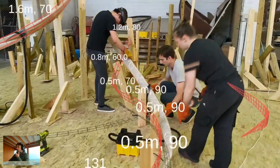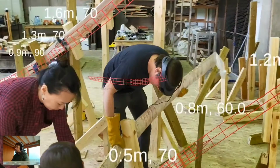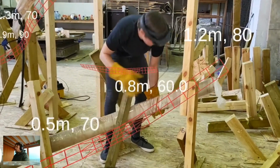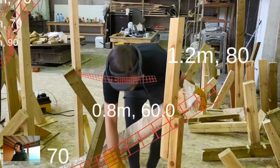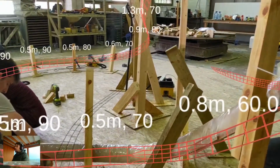So here's a short video showing you the actual fabrication process. This was fairly early on, I think, in the fabrication. And what you're seeing here is this is filmed through a mobile phone actually, but Igor is wearing the headset, and he's following this red strip which shows him the shape that this board needs to be while we're steam bending it in a bag. So essentially you have a 12-meter long bag with a 12-meter long part in it that allows you to keep the part really, really hot, which massively increases your work time. So if we took this timber out of the bag within sort of 20 seconds, it would be too cold to bend. In the bag, you get more like sort of 5 minutes to bend the part, which lets you keep it fairly accurate.